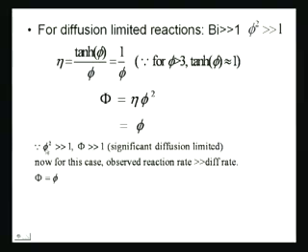It means that if phi square is much larger than 1, the reaction is very fast in the system, right? So, the reaction is very fast, and as a result the concentration is not going to be very high inside. But still, if there are internal diffusional limitations present in the system, there is going to be a concentration profile; it is not going to be uniform. It is not going to be a very high number, but even without a large number you can have a profile. You see what I am saying? So, that is what it is trying to say. It is not a uniform number, there is going to be a profile, but it is going to be a small number because the reaction is very fast. Okay. So, this is what we get.